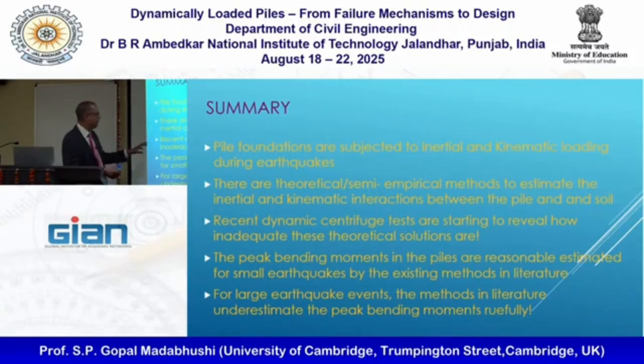But more importantly, we learned that if you design the experiments, you can get at least validation or otherwise of how good these solutions are. And I hope I have shown you that just by considering bending moments, nothing else, we could show that the existing methods work reasonably well for small earthquakes, but fail miserably when it comes to large earthquakes.